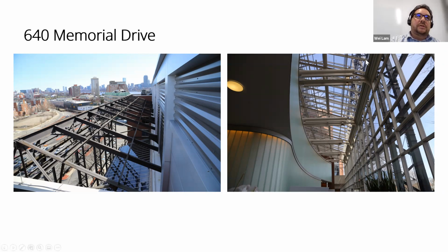But one of the interesting things is that there's remaining steel structure that was original to the building. But they built a beautiful atrium slope glazing in one of the last renovations of this building. I put these two pictures up here because the glass lights are starting to fail. There's a lot of deferred maintenance in terms of sealants in the slope glazing. And this giant steel cage prevents any sort of direct access, right? Very difficult to get in there and do anything with a lift. And so we're still trying to figure out how we're going to access some of these conditions in a practical and efficient way.